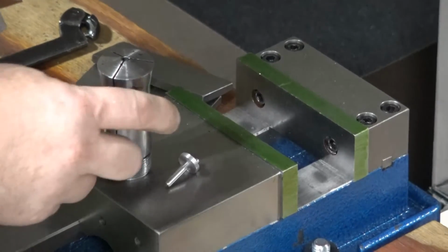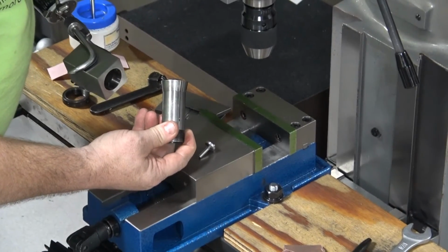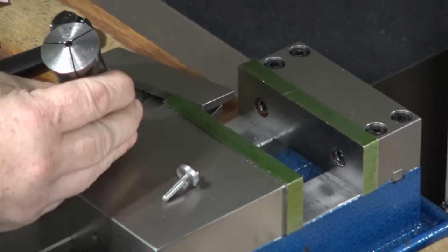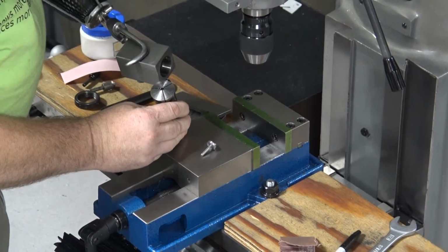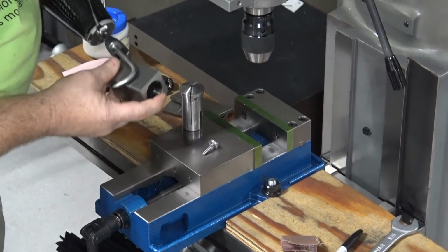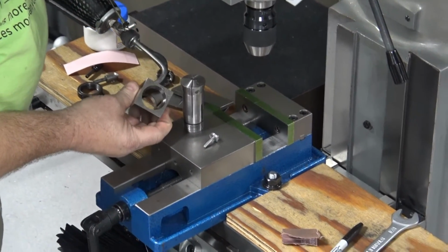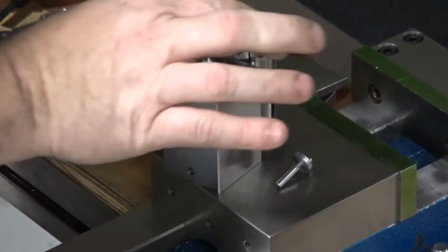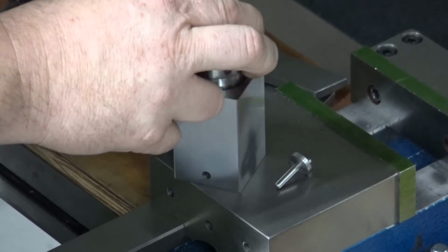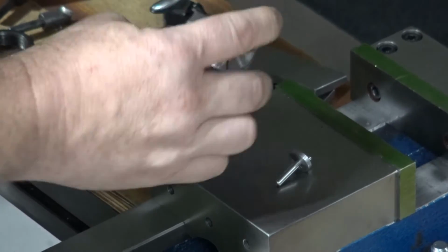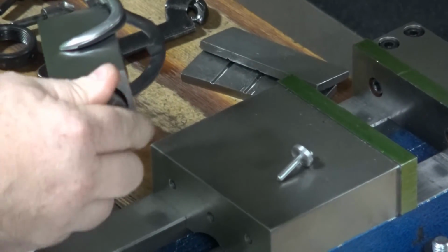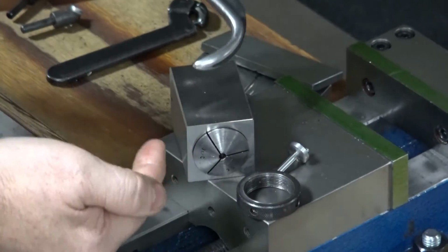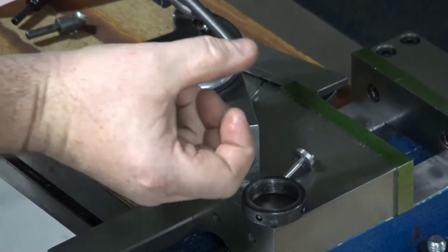This collet block, if I look at the shape of that collet, it's got a taper on the back side, right? Precision hole on the inside, maybe a little less than precision because students have used this and put little marks in it. But if I look inside the collet block, there's a taper on the inside of the collet block. So that means when I feed my collet into the hole, I want those two tapers to line up, right? If those two tapers line up, now when I put the nut on the back side and I pull that thread, it's pulling the collet back in, it closes up on the hole.